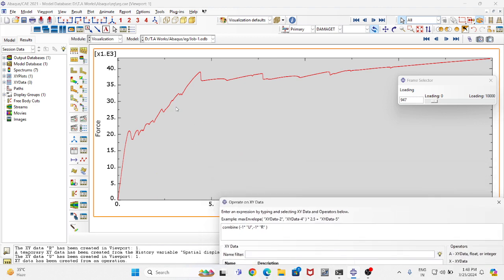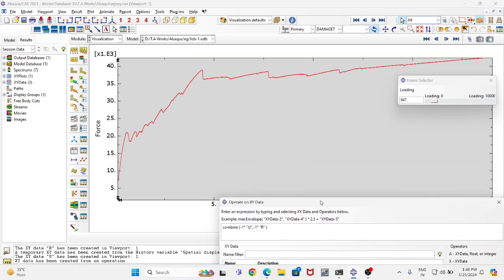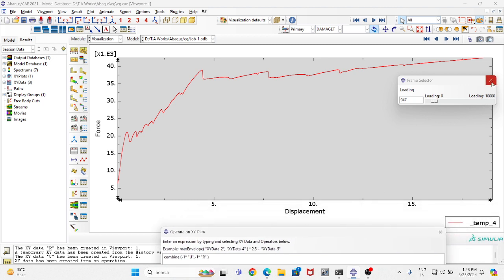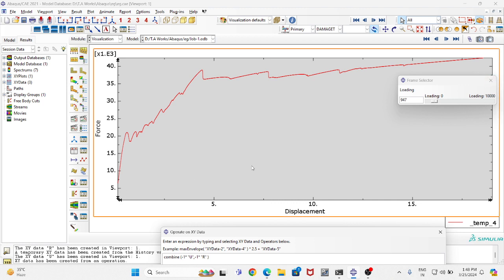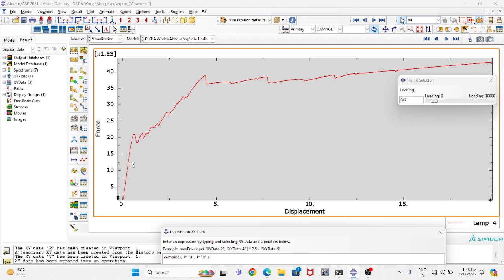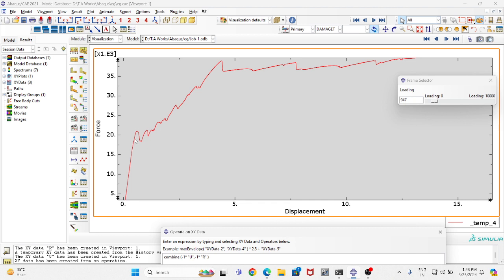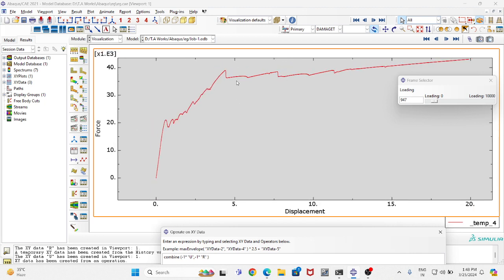Here, now this is the force displacement curve of my experiment. We can see it started in the linear phase, and the linear phase continued until it reached the initiation, it looks like here, of a kind of non-linear behavior. Now the first crack, any crack that initiates on the beam, will be reflected here in the graph. So anything that comes down means a crack. Then again, stress is being redistributed by the reinforcement. Cracks again, until we reach yielding.